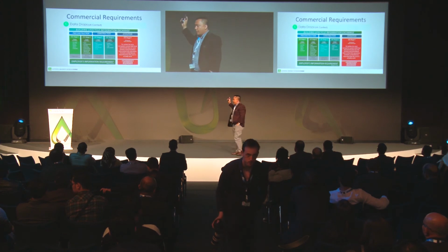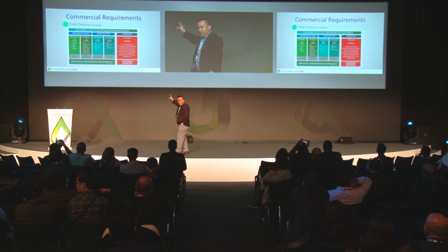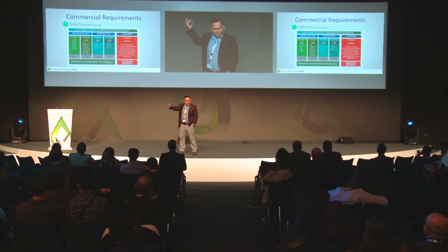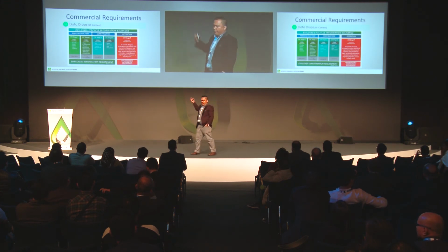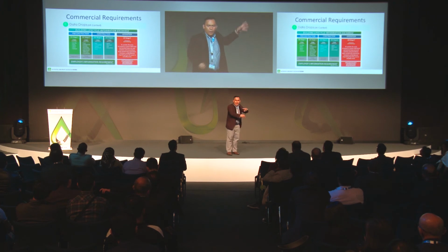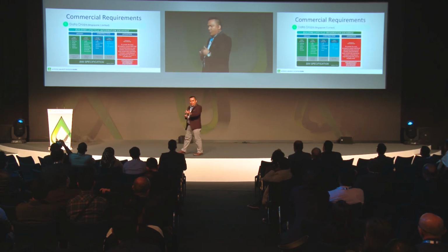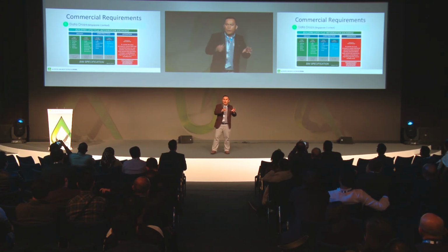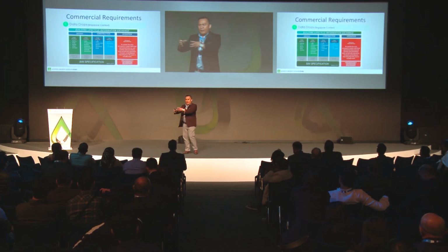So in UK, there is a concept of data drops here through Employer's Information Requirement, or commonly known as the BIM Specification. So at CIC stage 1, during the preliminary design stage, you have all this information, facility, floor, zone, conduct. These information should be propagated and submitted by the contractor for us to validate and review and verify if those information have indeed complied with our information requirement. Now this concept here, this context here, we actually adopted this one in Singapore. So in Singapore, we have the delivery of COBie information is during preliminary design stage, detailed design stage, construction, and as-built. Okay, so we did this one because for us to have a gateway to check the information. Okay, because there's no use that you check the information during as-built.